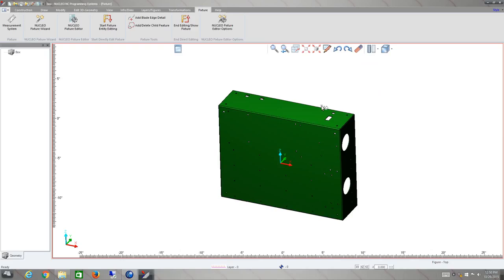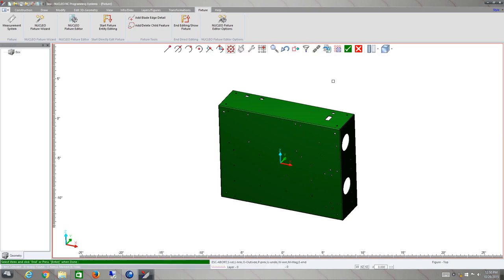One thing to remember when you're using the software, you may sometimes need to manipulate the view. For instance, if I wanted to delete this box, I can click the delete icon, and it's prompting me for the items to pick in 2 places. What I might want to do is get to a component or an entity on the back side of this box, but I can't see it right now. So the little shortcut to get around that problem is to keep the shift key down.